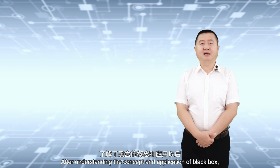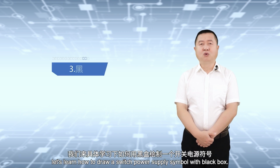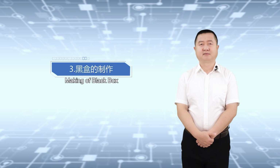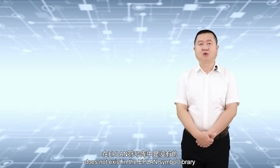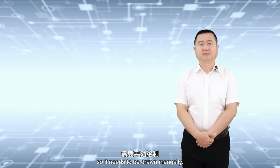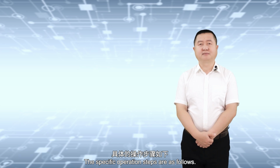After understanding the concept and application of black box, let's learn how to draw a switch power supply symbol with black box. The symbol of switch power supply for PLC does not exist in the E-Plan symbol library, so it needs to be drawn manually. The specific operation steps are as follows.